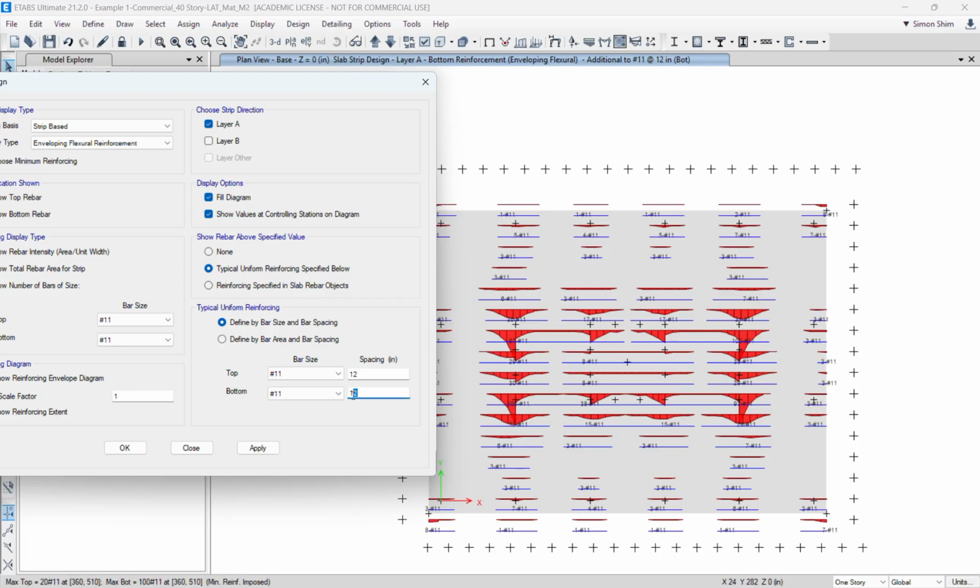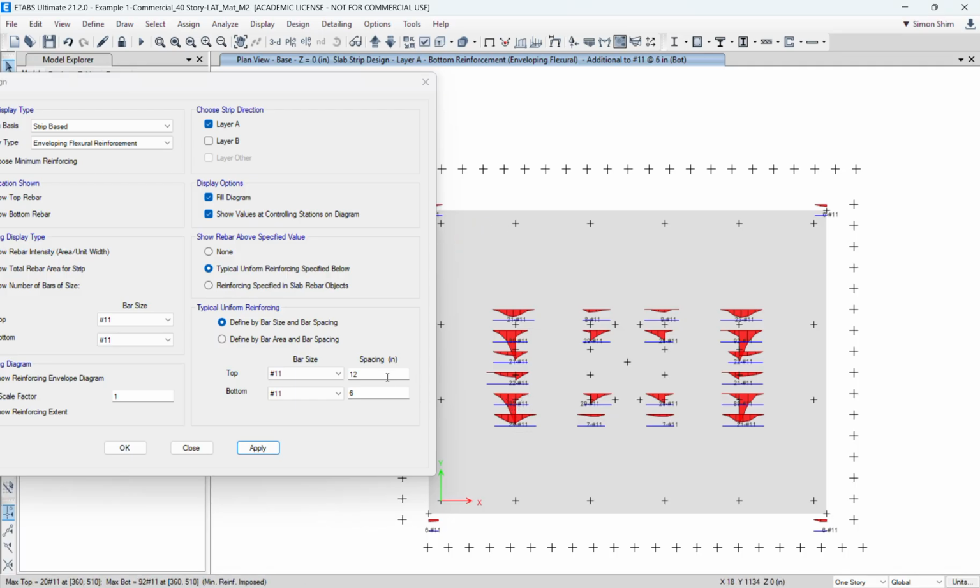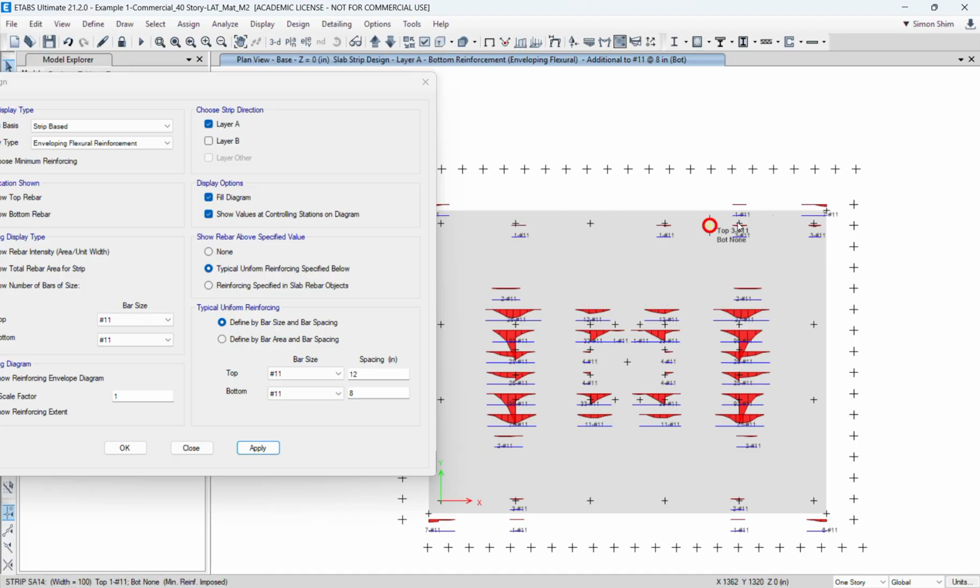So maybe you could consider, for example, 6 as a bundle, or maybe that's too much over, maybe 8, something like that. Because the number of bars is not always going to be clean. So you see that we need some more amount of rebars under the concrete wall, because a lot of the forces coming from the wall eventually require a lot of rebars.